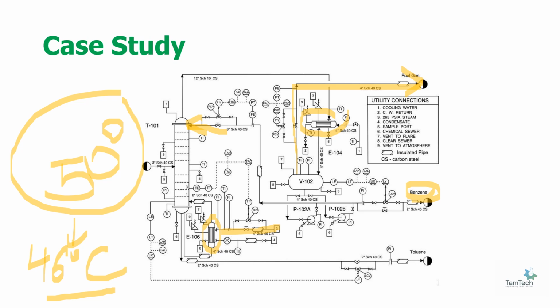But sometimes there are different ways. For example, if your bottom product is not used anywhere else, and it could be sent to the preheater, let's say, I'll draw a preheater, and this will be sent as a feed, then you have a second option. You increase the outlet temperature of your preheater.